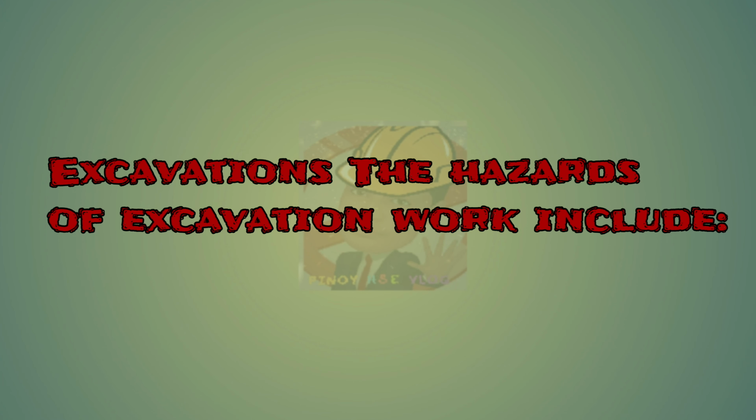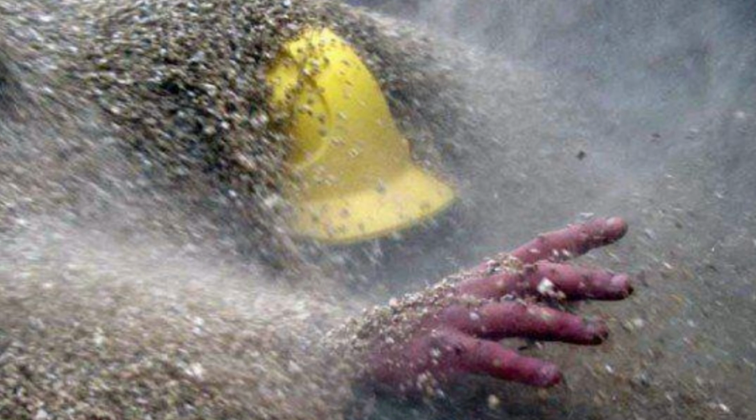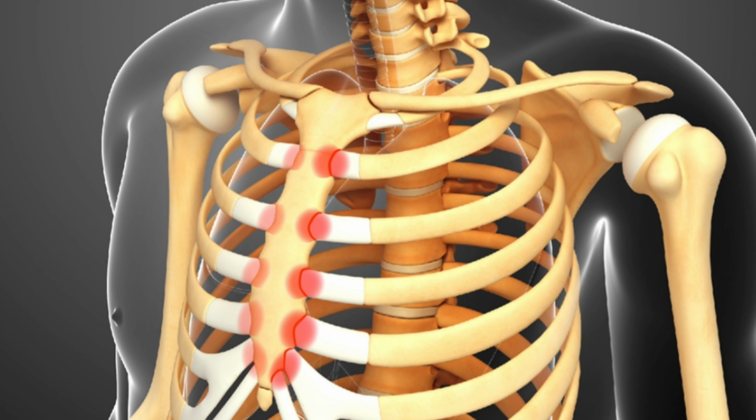Excavations. The hazards of excavation work include collapse, when the unsupported sides of the excavation slip and cave in. Severe crush injuries can result from even relatively small collapses because soil is very heavy. Workers buried or entrapped in soil can asphyxiate in minutes. Workers do not have to be completely buried for asphyxiation to occur. Being buried to the chest will lock the rib cage and have the same effect.